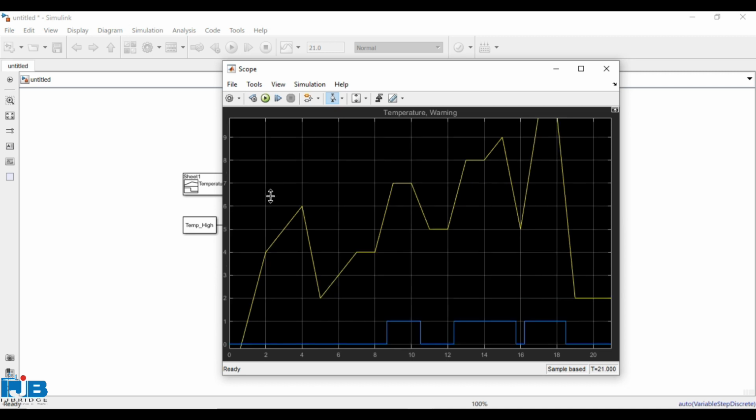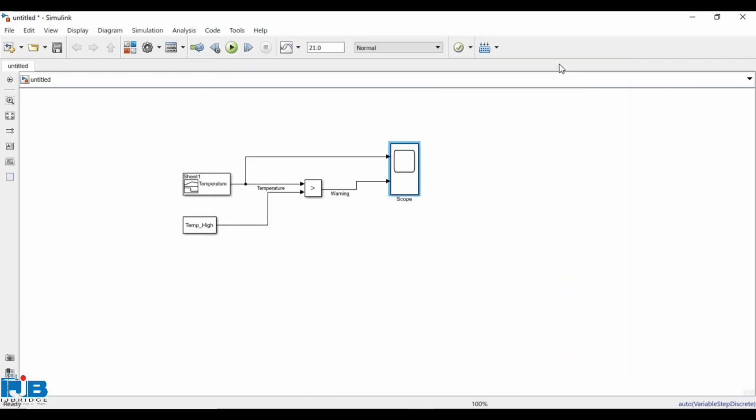Now here you can see the value 7. So whenever the output is higher than 7 or equal to 7, I am getting here output is 1. As it's a variable step input, I am getting the result at the same time it starts increasing towards 7, so it is more accurate. So the model output is as per the expected output. So this was the use case for parameter and signal in Simulink. Thank you for watching the video.